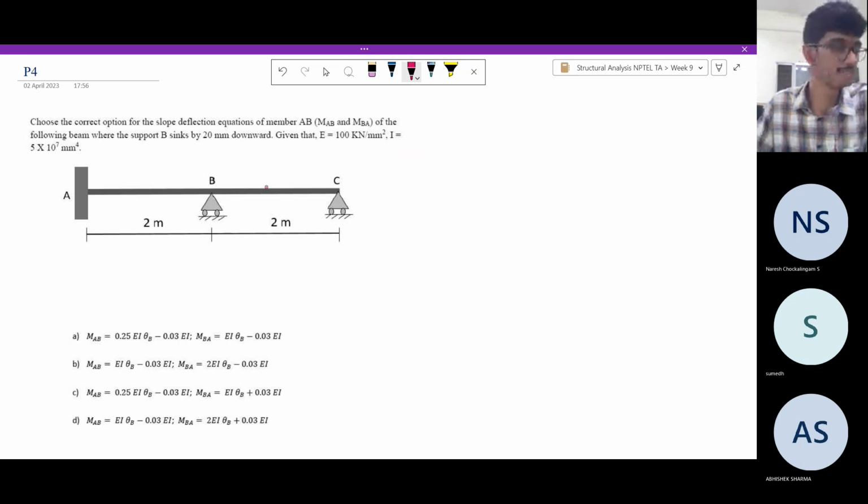So this is an even simpler problem. There is no applied loading. Now you will see how fast the method is. We don't have any applied loadings. It is statically indeterminate to the second degree, and it is kinematically indeterminate to the second degree. I hope you see how there are two intermediate reactions which are redundant. So NS is equal to 2.